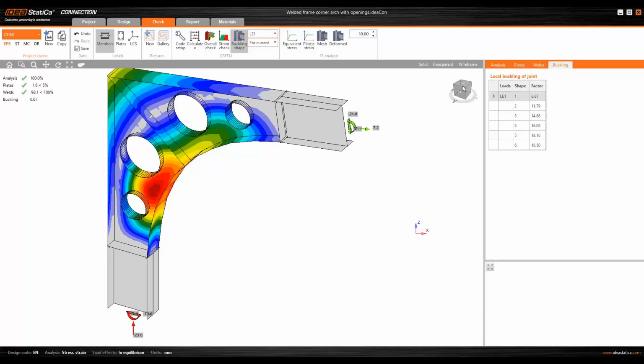So we have to discuss a little bit the buckling factor, or the factor of the critical force, as it is correctly called. And actually these values, or the value that you have to fulfill, is defined for different codes, and it's a little bit on the decision of the engineer.